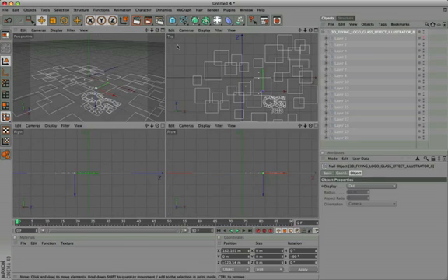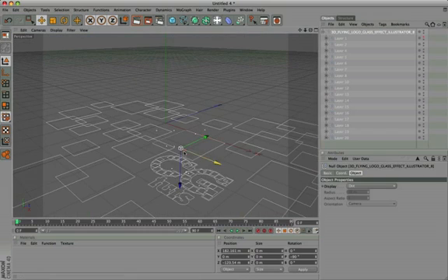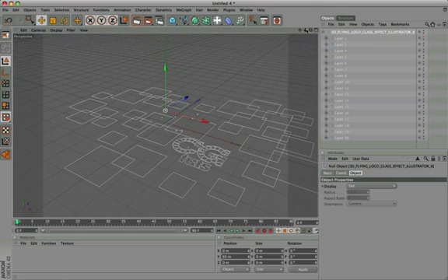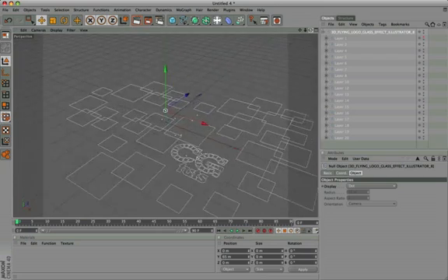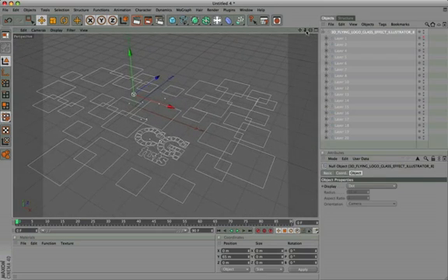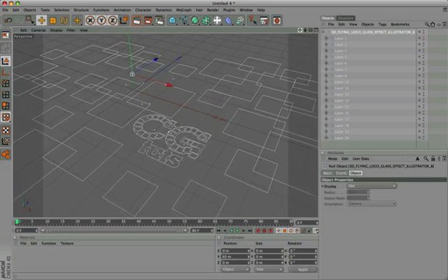Now reposition the pivot of our object in the center of the scene. Go to Move Tool Pivot, and place 0 value in all the coordinates, to place the pivot at the center of the scene. Now we can change the Y coordinate to value 65. This is because our object is not resting on the floor, but is suspended, in order to get softer shadows and caustics.